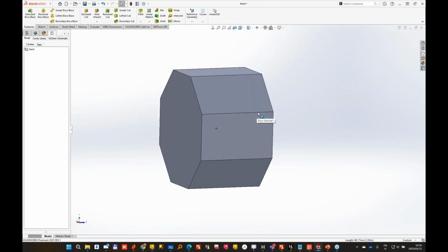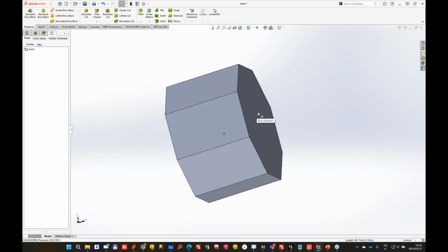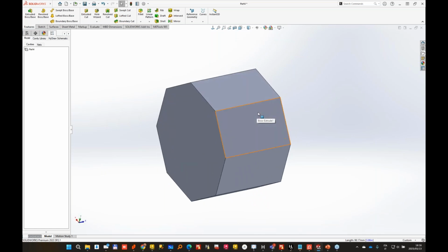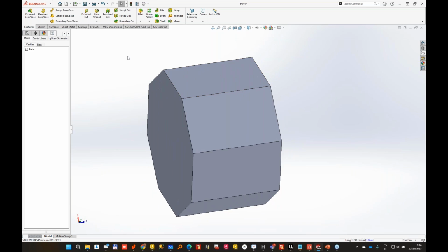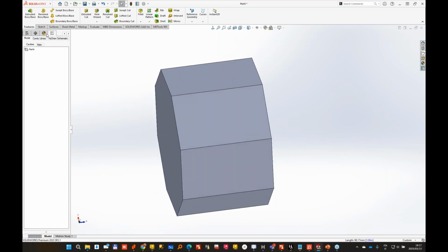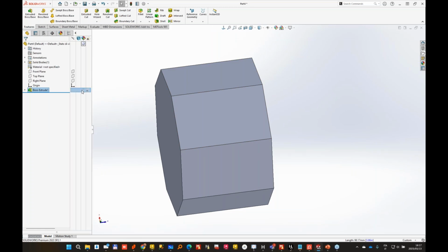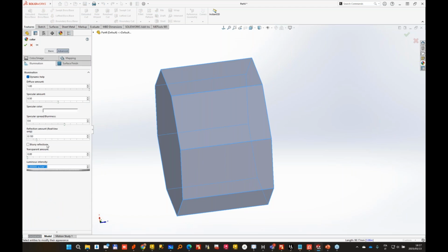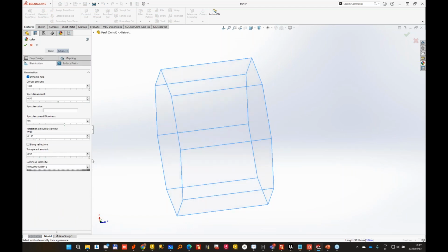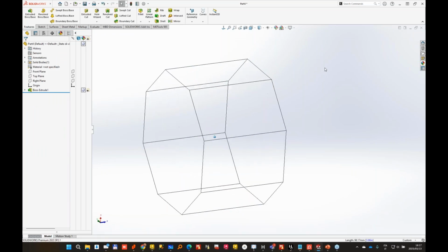MDTools works better with the transparency on. In Inventor, it's done automatically. We work in wireframe and virtually color the block. In SolidWorks, it's a bit different. We apply transparency. For those who are not familiar with this aspect, in order to make this part transparent, you must go to the SolidWorks feature, expand it, and go to the appearance of the extrusion. Here we go to the advanced illumination, and we can bring transparency up to 100. Usually I like to work with 100% transparency.